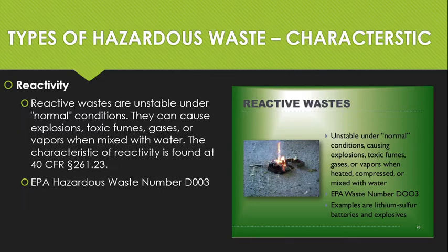It's a special category of hazardous waste where they made the rules easier for generators to manage their waste, where they don't have to classify it as hazardous. But like I said, if it's something that has an explosion threat or toxic fumes, gases, vapors when mixed with water, then it's going to carry this code, D003. So once again, that's an indicator to us and to the disposal facility. When they see that code, they'll say, okay, this is reactive. So we need to be careful, it's a hazardous waste.